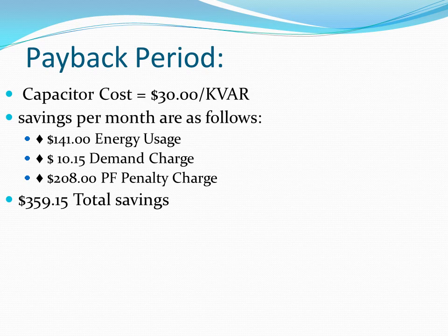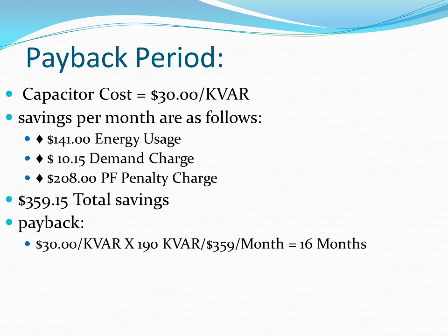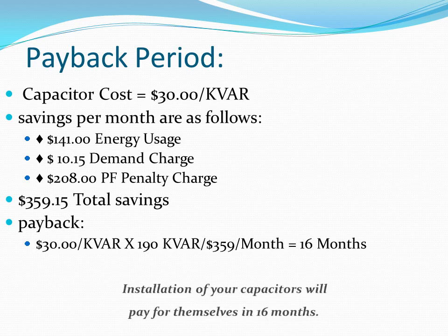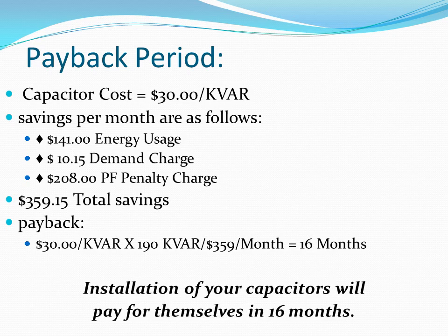These result in a total savings of $359.15. So your payback period will be the $30 per kilovar times 190 kVAR divided by $359 per month, which is 16 months. Installation of your capacitors will pay for themselves in 16 months.